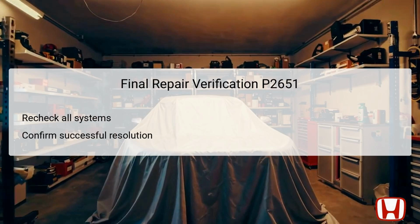Upon completing all necessary repairs related to DTC P2651, it's imperative to conduct a final verification to ensure that the repair was successful and that the issue has been fully resolved. This involves rechecking all systems involved in the VTEC operation and specifically monitoring the oil pressure switch.